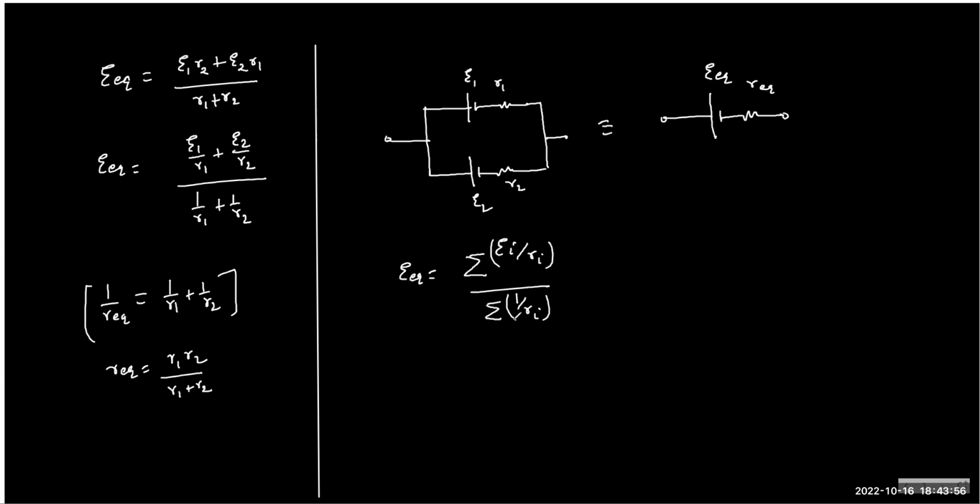You can choose right as positive, left as negative, or left as positive, right as negative. If the final answer is negative, it means your assumption was opposite of the actual. If the final answer is positive, it means the way you assumed was correct. So no need to worry about the assumption. You can choose whatever assumption you are happy with.